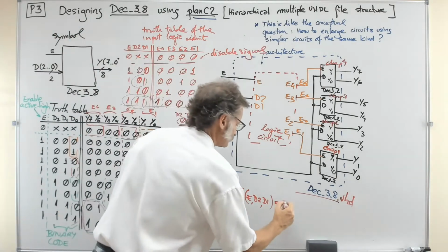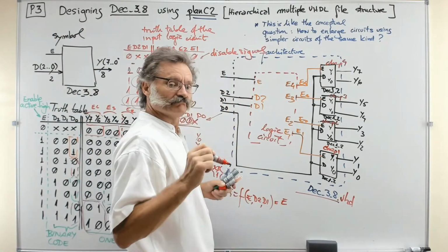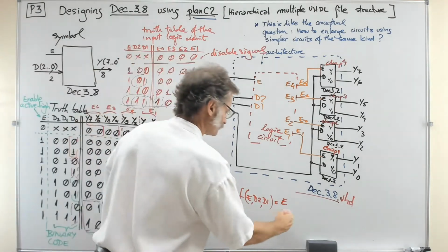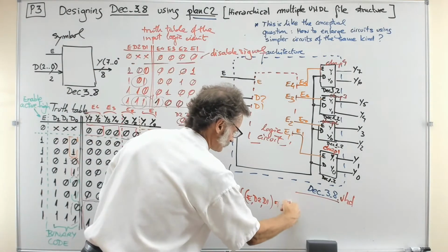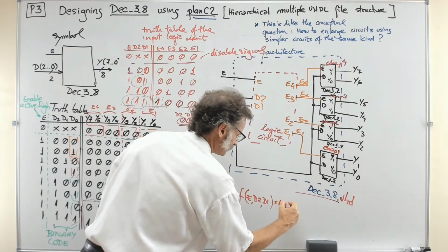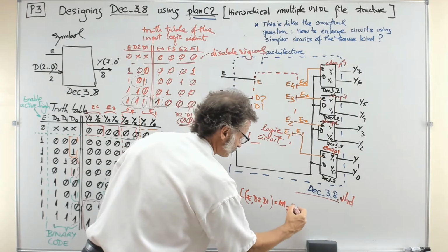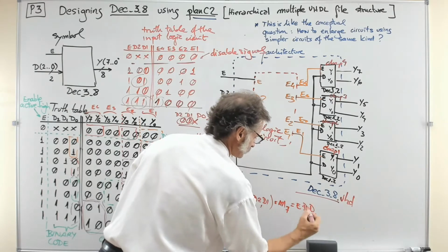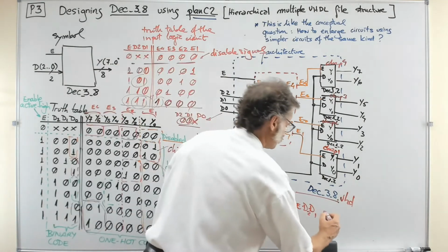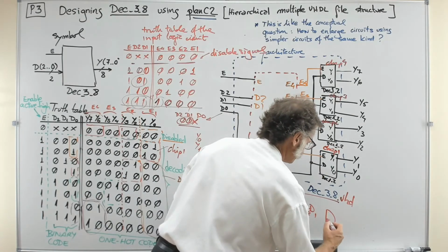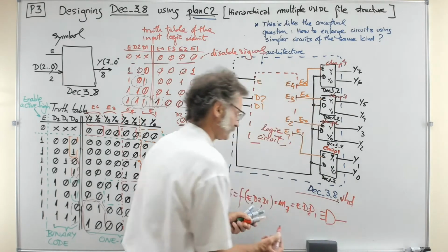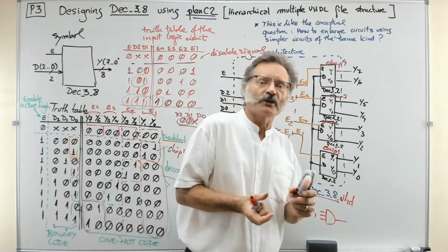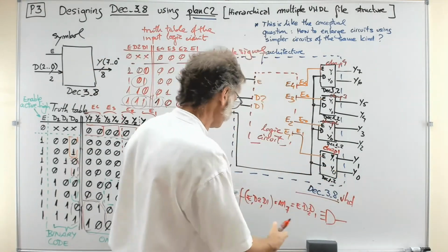111. So this is a single min term, the min term 7, of this function. You may write that very well exactly as the min term 7, m7, and this is E, D2, and D1. So this is a simple AND of 3 inputs. That's the circuit that you have to draw here, but you will not draw it, but write it in the VHDL in the end.